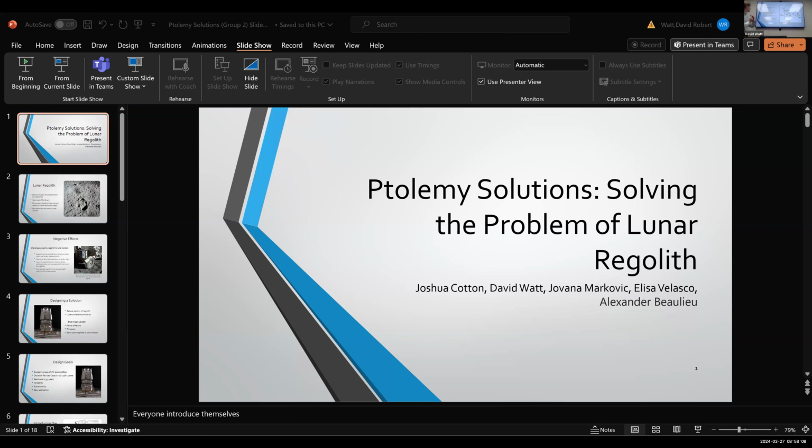With it being fixed, the total stress added from the tarp to one individual hook was 20.64 megapascals. And the material chosen, like Giovanna mentioned earlier, was aluminum 1060-0, and that had a yield strength of 30 megapascals. And applying maximum shear stress theory, the factor of safety is derived to be 1.45.